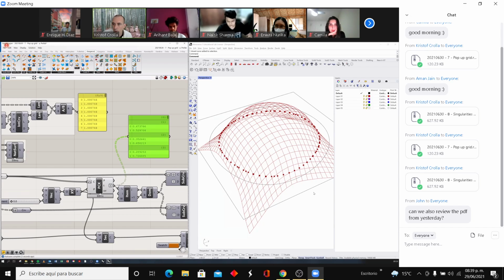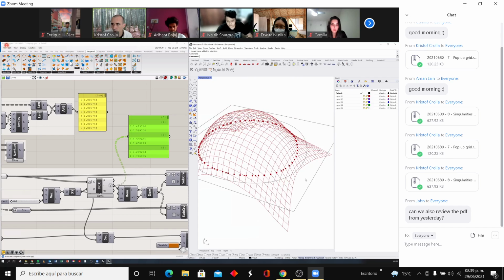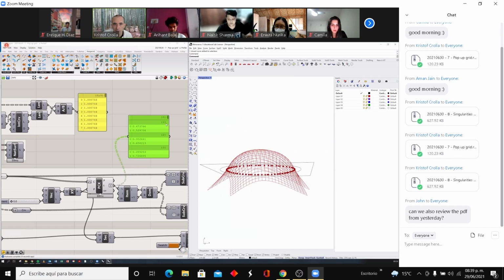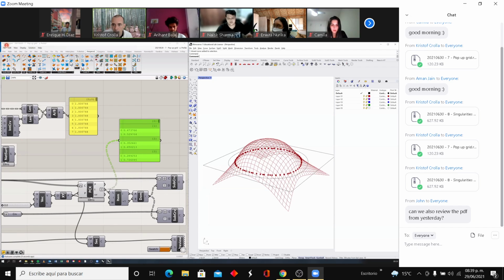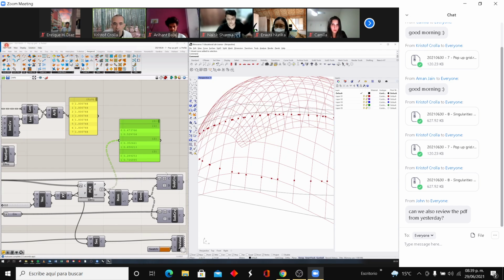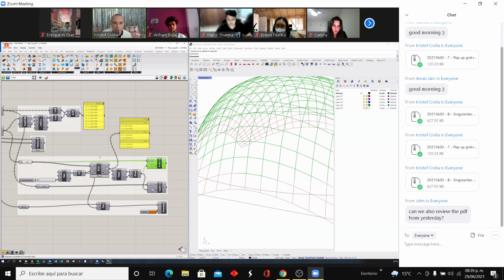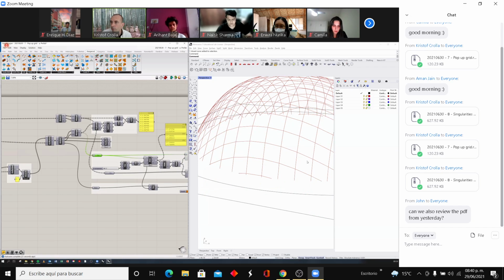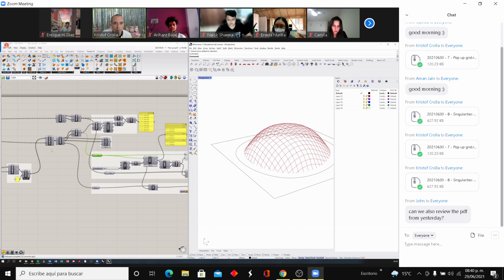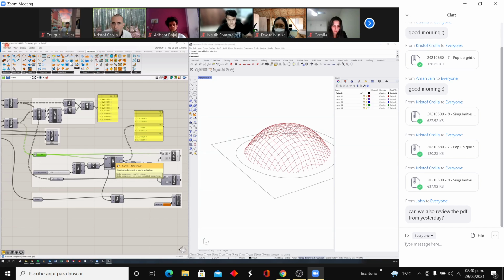For example, curve 0, which is entirely underground here on the right, does not have any intersection point. But as soon as we're at curve number 1 here, there are 2 points where it intersects with the ground. That specifies a domain that I can use to derive a subcurve from my original curve set. So that's the subcurve I've taken just by intersecting each of my input curves with a cutting plane on the ground. This is a very quick calculation because curve-plane intersection is a mathematical formula. It's not a physical analysis, so it calculates quite quickly.